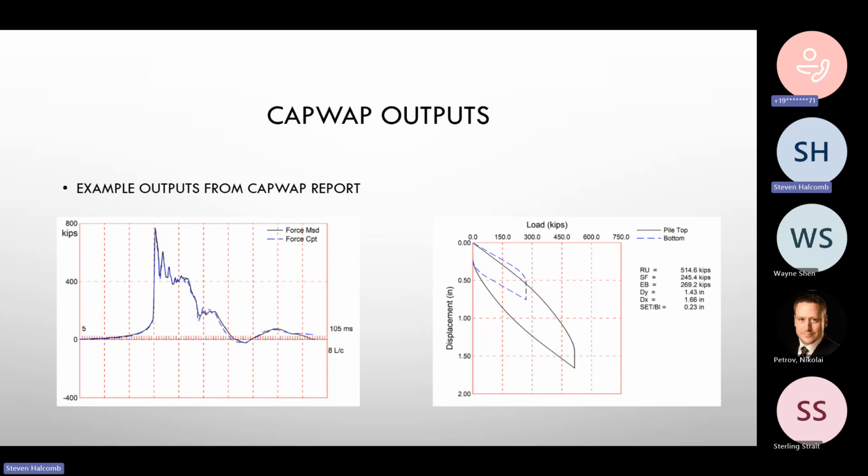output, the simulated load displacement curve and values on the right are what you also see, and you can see where it breaks down the total resistance, the skin friction, and the end bearing, and then at what displacements you would need the dy and the dx. Usually those are about the same, because they're pipe piles, so there are no differences there. And then the set is just the set. That's basically the blow count, but inverted.